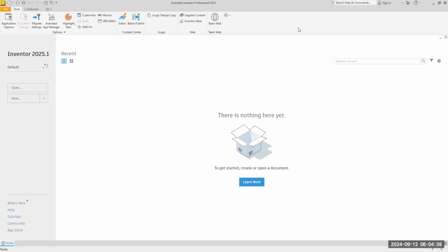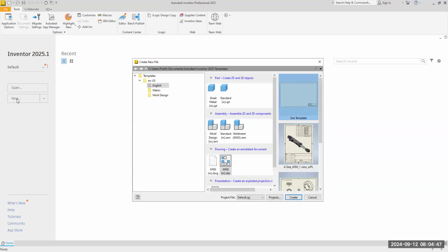So when you open up Inventor, this is what you should see. I'm going to go to New. Select New. I'm going to go through this very slowly, like I have with the other videos. If your screen looks like this, for example, and you wonder where the English and the metric are, don't panic. It just means you need to expand. Click on this arrow and expand your choices. There's English right there. This is an English part. And yes, we are going to do some metric parts in here. So select English. And then come over here. We're going to create a 3D part.